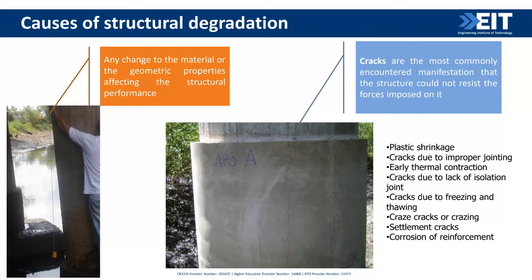We have cracks depending on plastic shrinkage, freezing and thawing cycles. Depending on your country, we can have different possible causes for cracking. In concrete, we can also assume problems related to inappropriate design and construction practice.